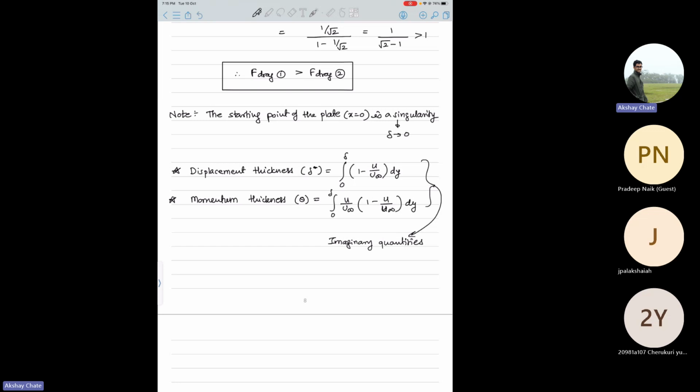There is another definition to it. They call it, displacement thickness signifies the mass that is deficient in the boundary layer because of the boundary layer formation, basically. So there are many definitions, but many a times I've seen people forget that it's an imaginary thing. They think that it should be somewhere in the diagram, but it's not. It's just an imaginary construct.